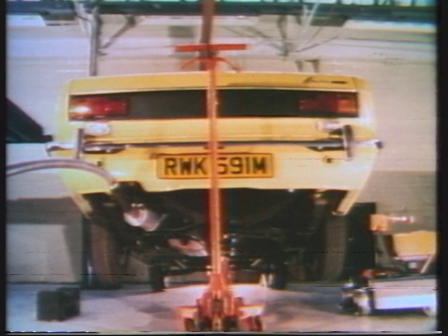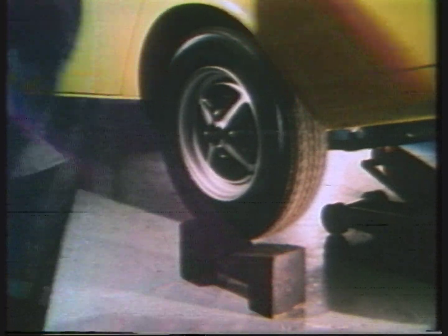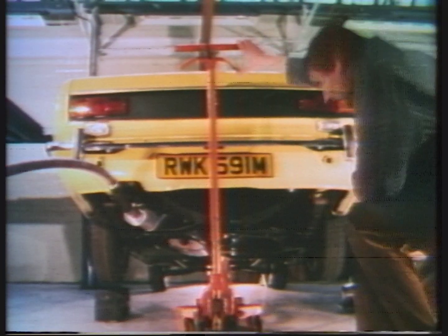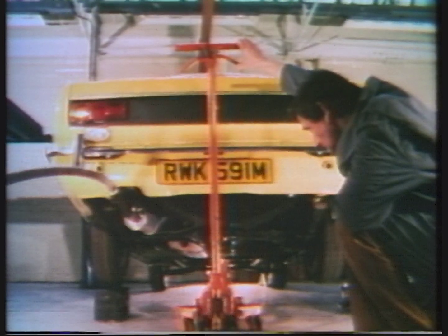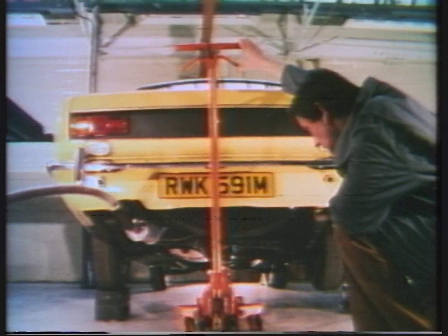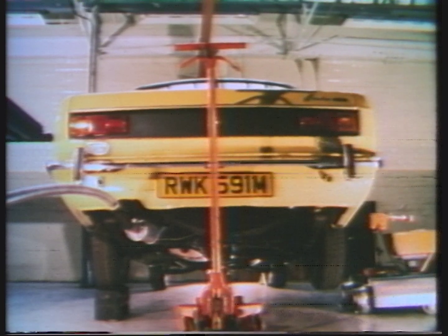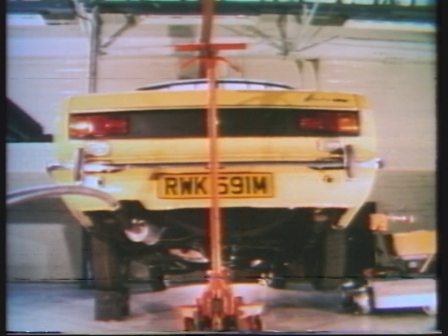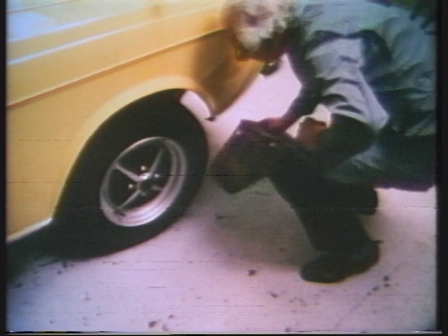Locate the jack securely under the differential and arrange so that one wheel is firmly held by a prepared wood block and the axle is level. The axle must be horizontal or lubrication of differential gears and bearing will suffer. And for safety, chock both front wheels.